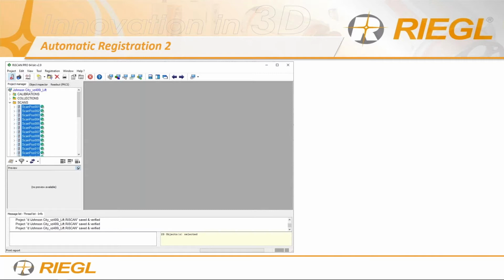And not only that, you can continue registering days after, right? So if you have a project where you have to spend 3 days scanning, you have 1,000 scan positions or more, you can register each day at a time, and then just keep on adding to it, right? So don't select the positions that you don't want to register, and just select only the positions that you want to register.